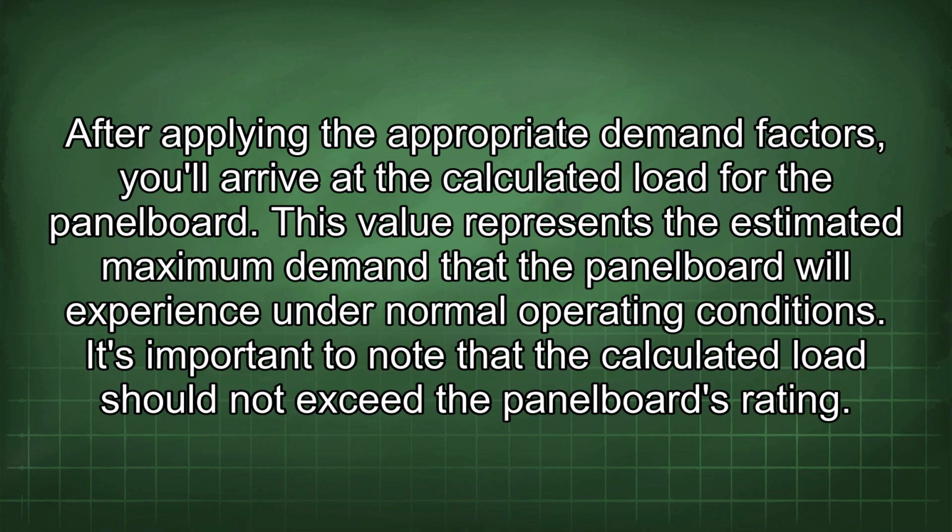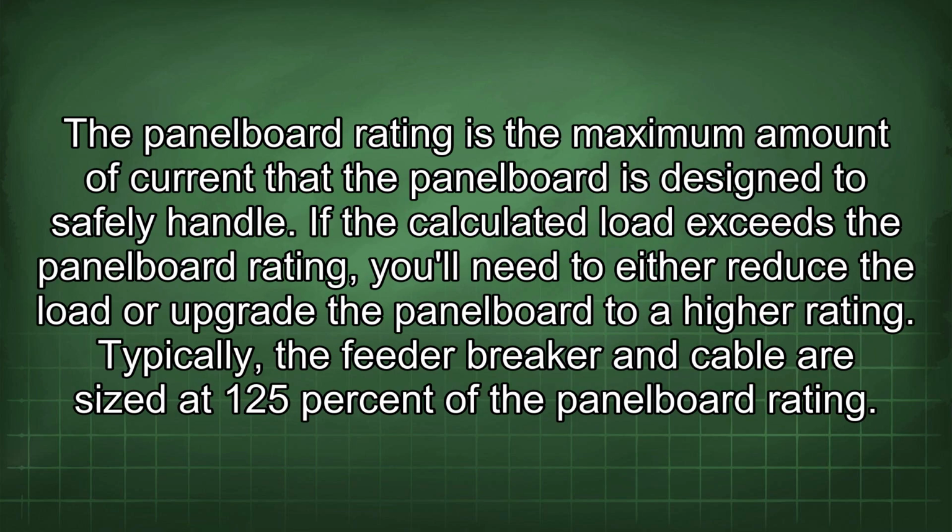After applying the appropriate demand factors, you'll arrive at the calculated load for the panel board. This value represents the estimated maximum demand that the panel board will experience under normal operating conditions. It's important to note that the calculated load should not exceed the panel board's rating. The panel board rating is the maximum amount of current that the panel board is designed to safely handle. If the calculated load exceeds the panel board rating, you'll need to either reduce the load or upgrade the panel board to a higher rating.